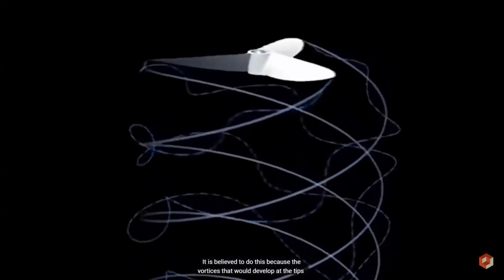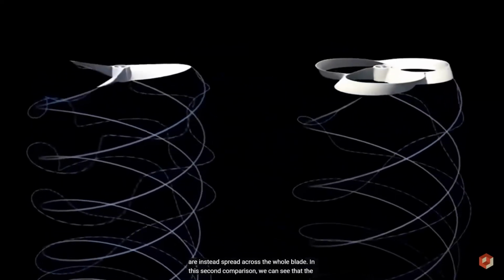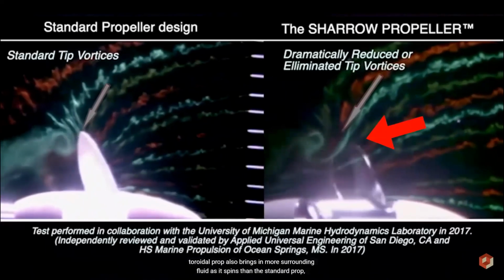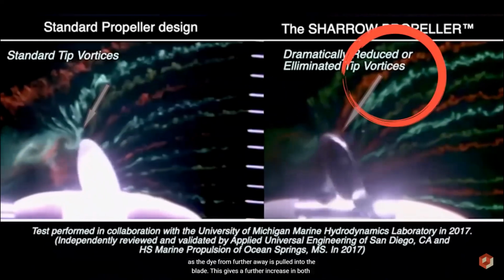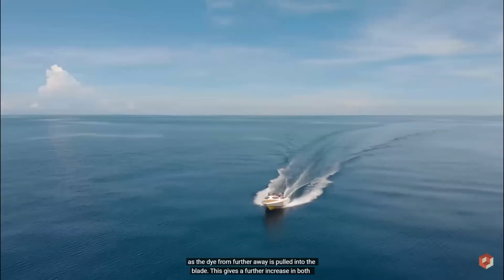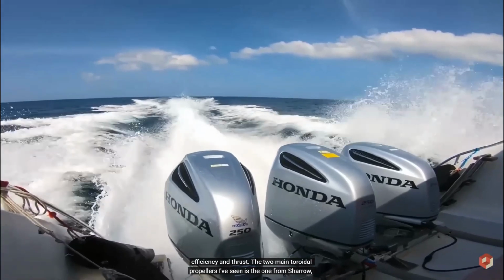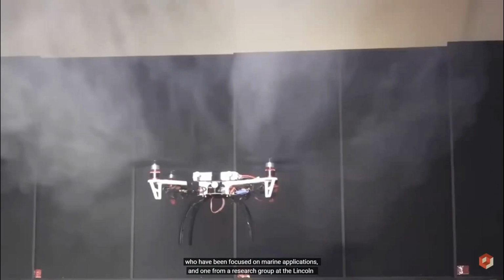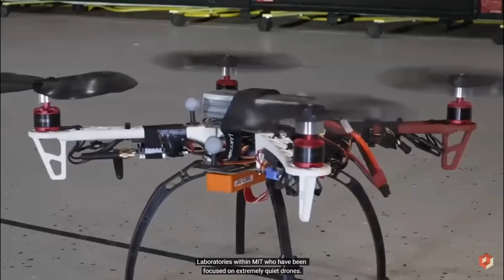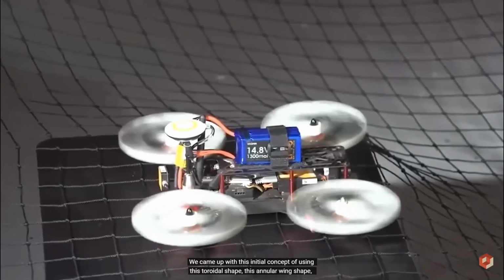It is believed to do this because the vortices that would develop at the tips are instead spread across the whole blade. In this second comparison, we can see that the toroidal prop also brings in more surrounding fluid as it spins than the standard prop, as the dye from further away is pulled into the blade. This gives a further increase in both efficiency and thrust. The two main toroidal propellers I've seen are the one from Sharrow, who have been focused on marine applications, and one from a research group at the Lincoln Laboratory within MIT, who have been focused on extremely quiet drones. We came up with this initial concept of using this toroidal shape, this annular wing shape.